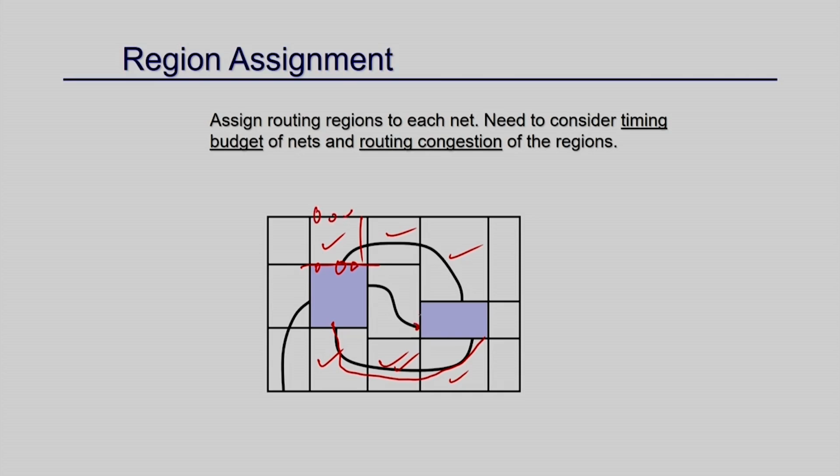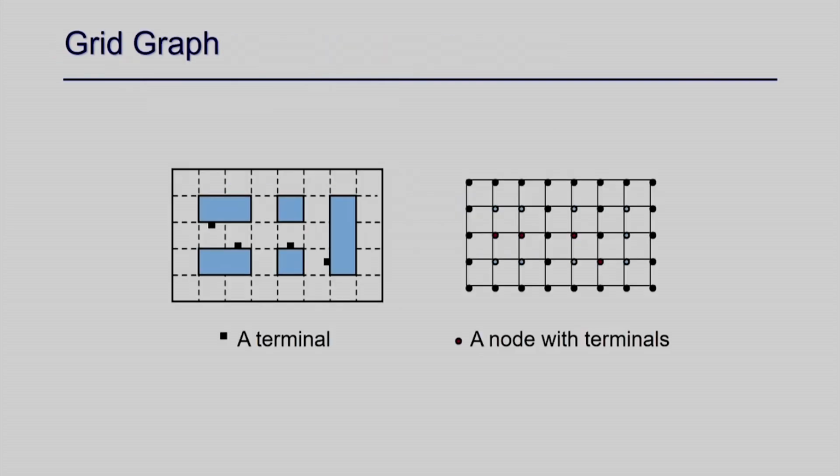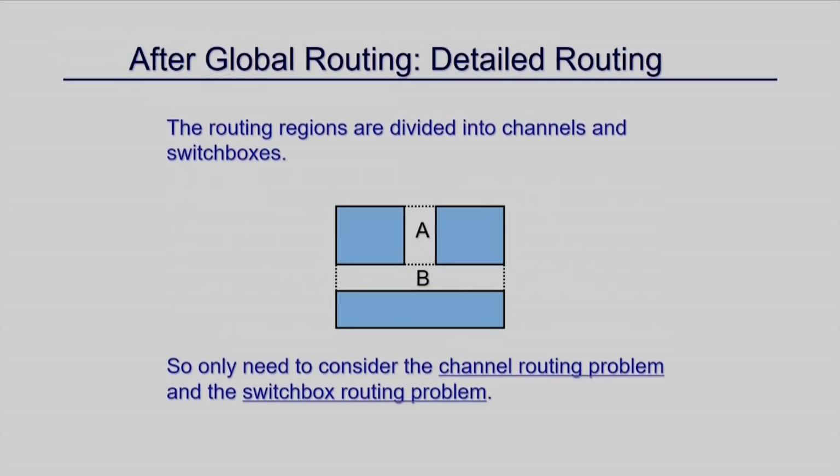Similarly, for this I know how many inputs are coming, how many pins are on this side. So, that is what is called pin assignment. After this you decide the pin assignment for each channel or switch box, and once this is done, I am going to go for detailed routing.